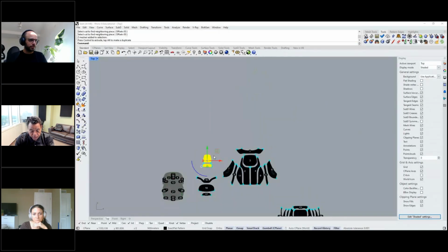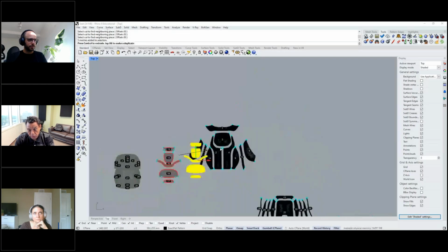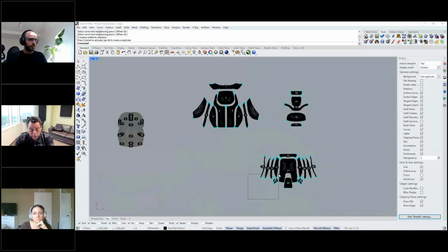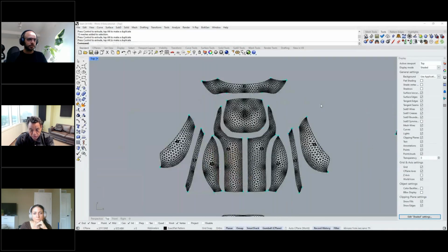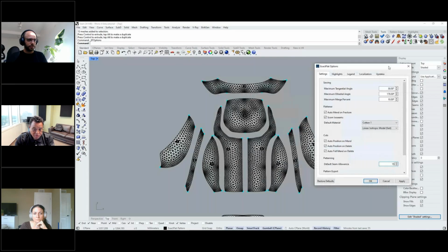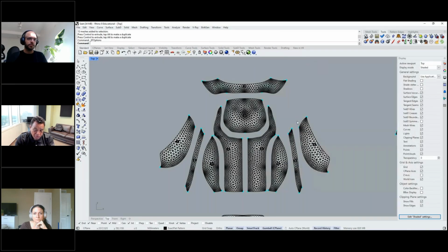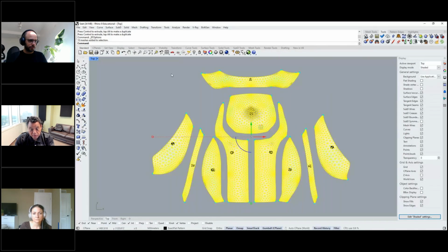visualize the sewing orientation. This will also be a huge time-saving factor when it comes to applying seam allowances and notches, because as you'll see very shortly when Gonzalo shows you, when you apply a seam allowance to one edge, it is automatically applied to the other edge. And the same thing for notches or a chain of notches. So your subsequent 2D pattern making processes will be greatly enhanced. In addition, because you don't have to walk the patterns to make sure that the edges align perfectly and the notches align perfectly, you're going to have substantially less errors.